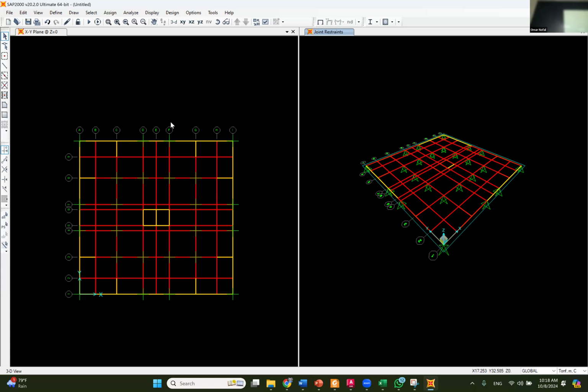So the column needs to be at the joints of the mesh. That's the mesh. The mesh only has 4 joints. Okay, one here, one here, one here, and it only feels load or deformation or anything at the joints. In between, there is nothing. It just makes some averaging in between. So if your column is here, the column is not feeling any load. The reaction is going to be 0. The deformation is going to be 0. Everything is going to be 0. But if your column is here, it's going to feel that there's a slab here. That's why we did this.